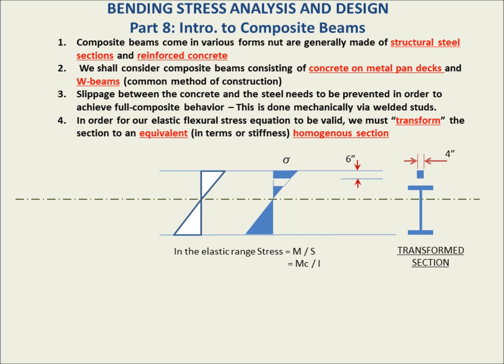What we need to do next is to locate the neutral axis of this new cross section, find the moment of inertia of this new cross section, and then use this flexural stress equation to find the stresses at any location along the cross section.